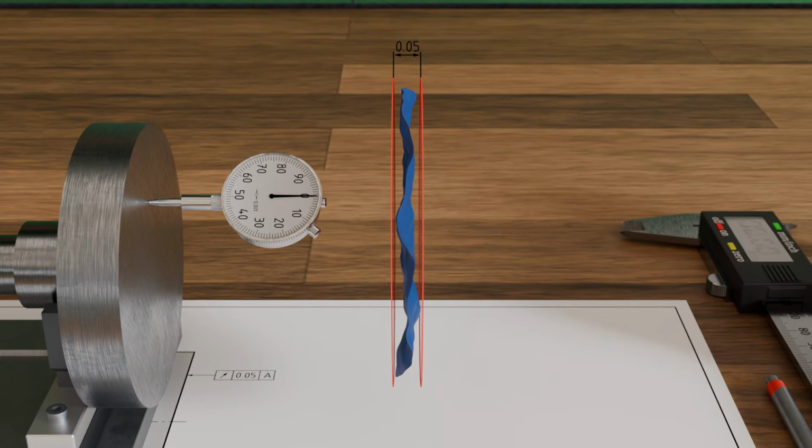Total axial runout also implicitly includes perpendicularity as an additional positional tolerance, because the entire surface must not deviate too much from perpendicularity relative to the datum axis. Otherwise, the surface wobble would be too great, and the axial runout would no longer be maintained. Thus, total axial runout also implicitly controls the flatness of the surface.